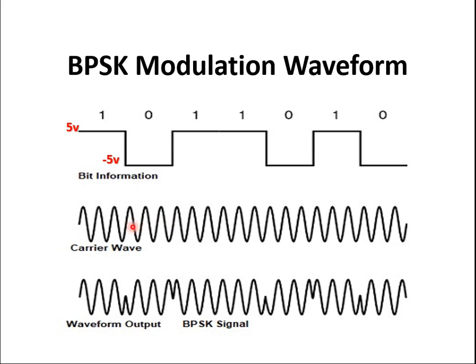From here to here, whatever the carrier is there, its inverted version is this one. After this, once again there is a transition from 0 to 1. This is my original signal, right? 0 to 1 transition means once again I will be multiplying 1 volt with this x, which will give me x only. So I am getting x.